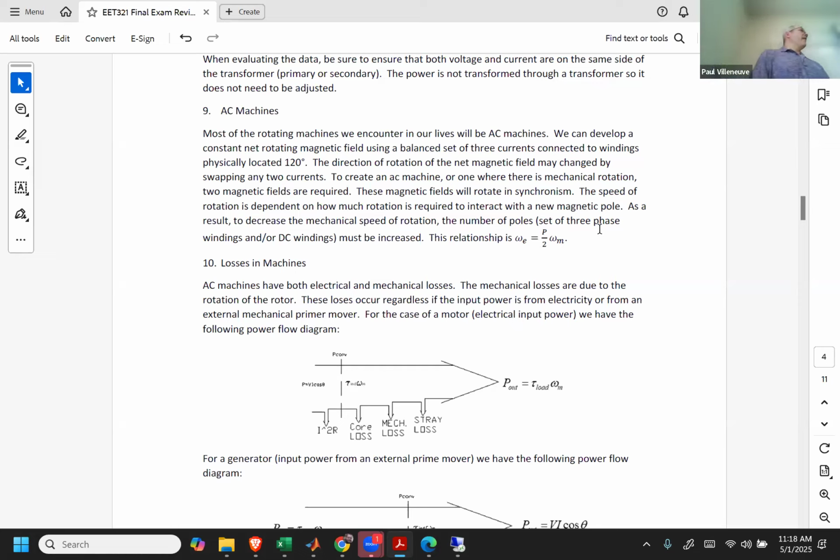And we then evaluated by saying, let's put more windings in there. And because we don't need a balanced system, we can't just add one. You have to add 3 sets of windings, right? Because all the systems have to see the same thing. And then when we divvied those up, we saw that the magnetic field only had to rotate another 180 degrees as opposed to 360 degrees to get to another phase A or phase B or phase C.